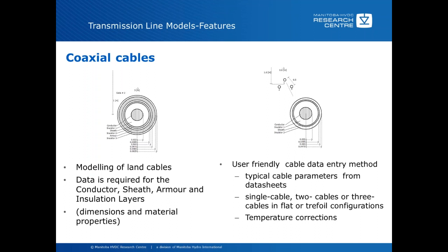Now I would like to discuss the cable models in PSCAD in detail. There are two types of cables. One is coaxial cable, the other one is the pipe type cable. So coaxial cables are used for modeling of land cables. We have discussed all these things. Data is required for each layer, dimensions, and the material properties.